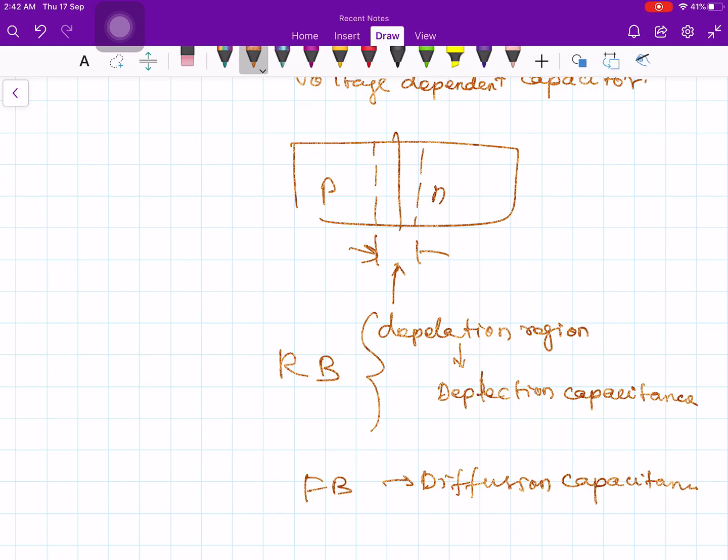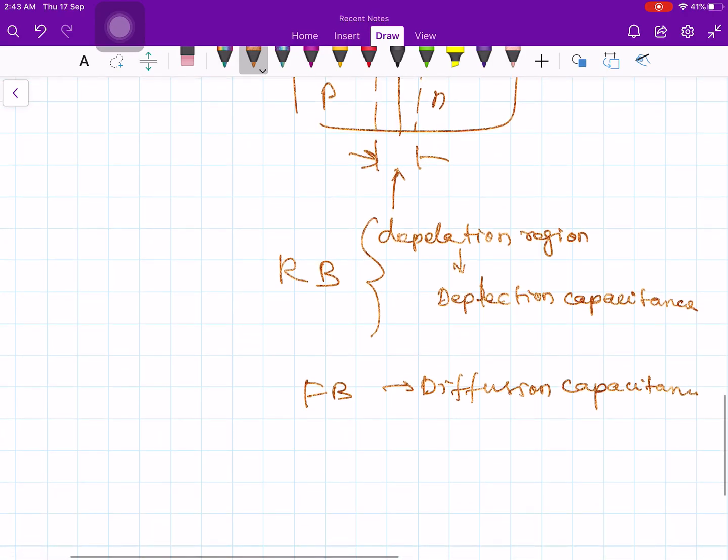So you have a capacitance, and that capacitance depends on the applied voltage. The relationship between the capacitance available from the diode, or from the device, and the applied voltage does not have a linear relationship. There is a square root kind of relationship, but let us assume for a moment that we have a linear relationship. So basically our capacitance C is equal to some initial capacitance C naught, the nominal value of the capacitance, minus some constant K times m of t.